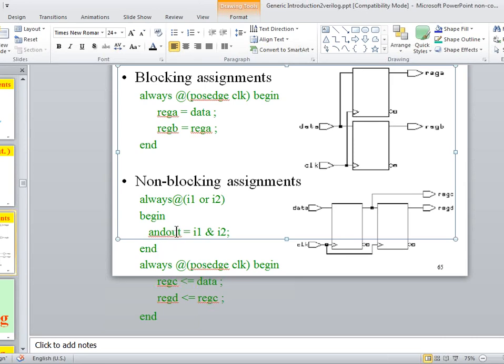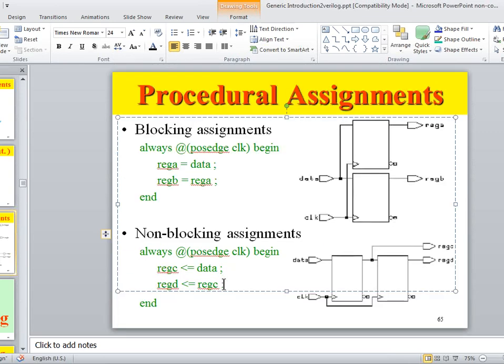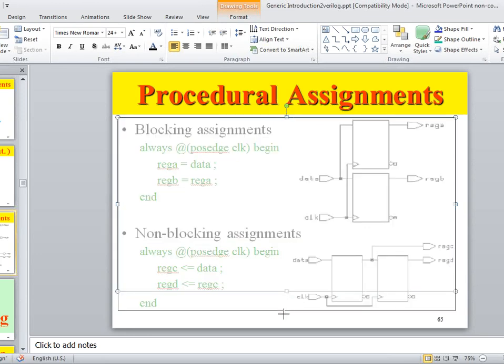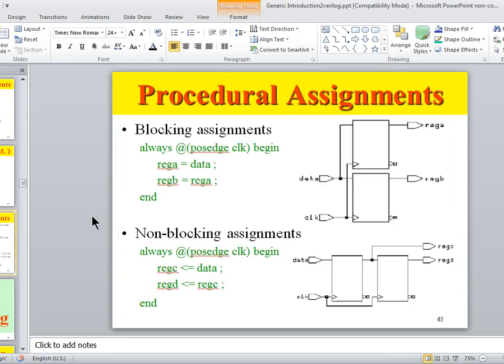Since there is no flip-flop, there will be no delay in the gate output. It will work on the passage of the clock and get updated immediately, even though we are including it in the same always block. But this is another method, where you can create a separate always block for your combinational circuit. So that's the solution in case you want that. Any questions?